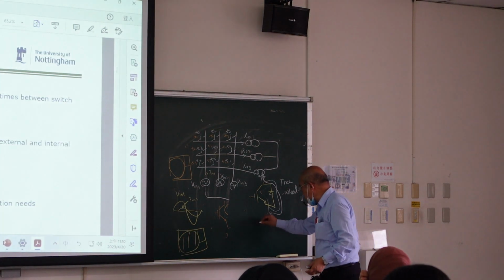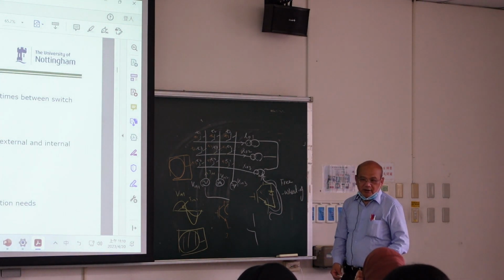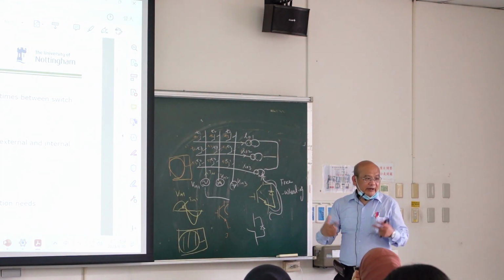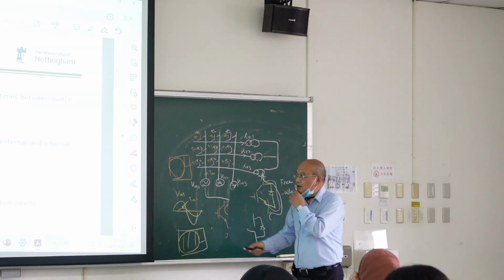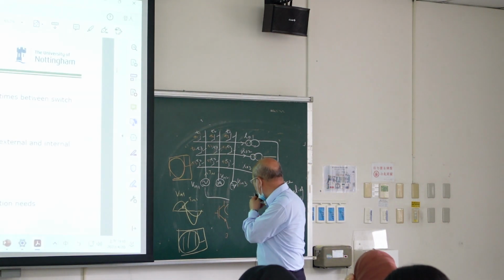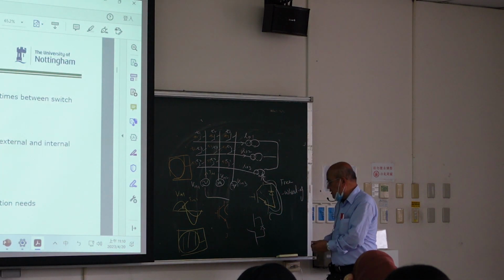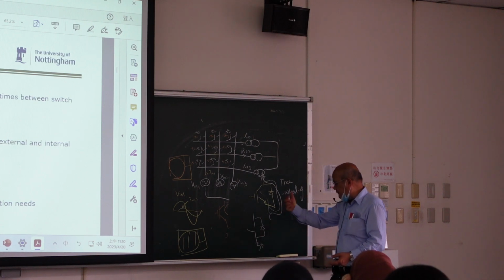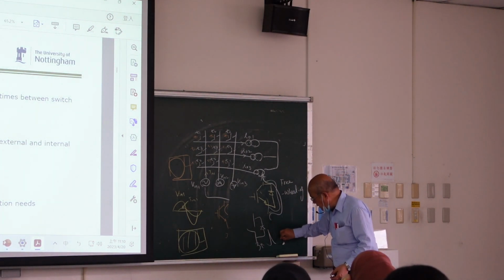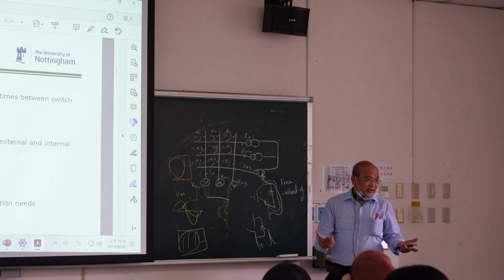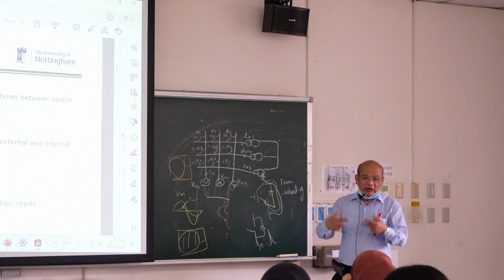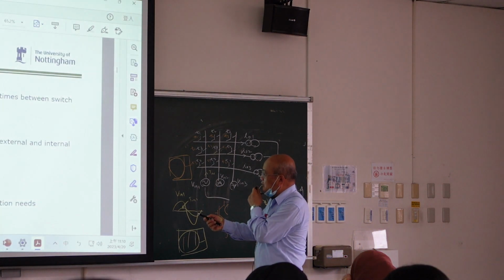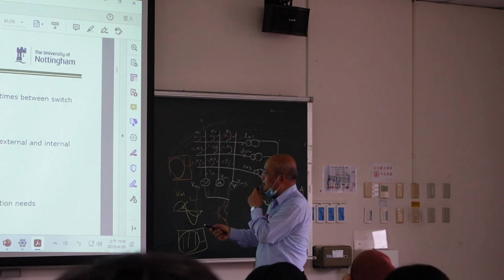But if you have an AC switch, can you put a diode here? No. So you have no free-wheeling diode. Then if the switch turns off and you have inductor current here, but you have no diode, then it creates a spike, then damages your device, right? So you have no free-wheeling diode. This is a disadvantage when you have that type.